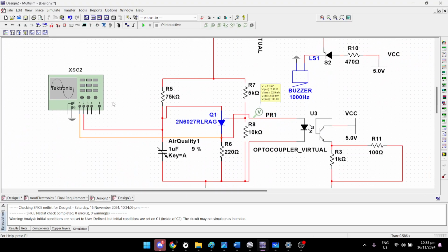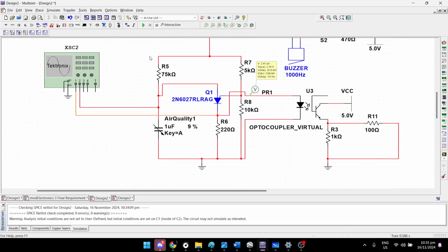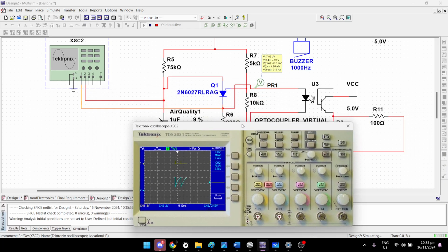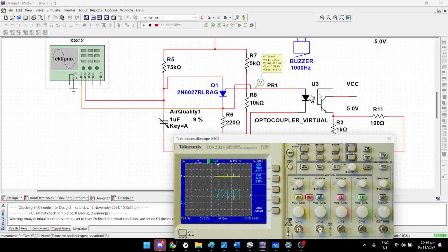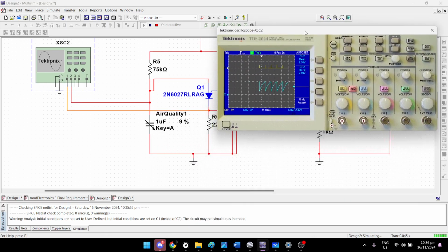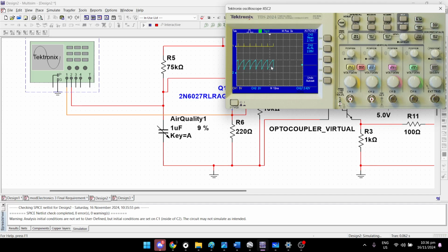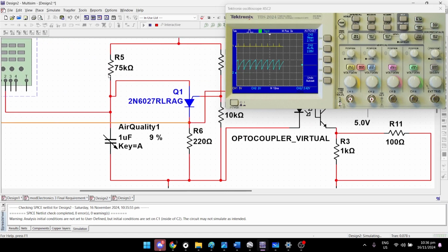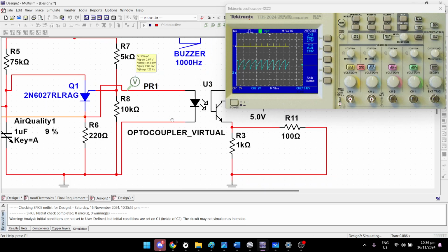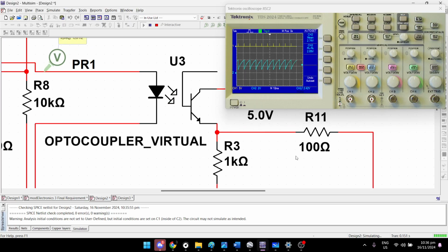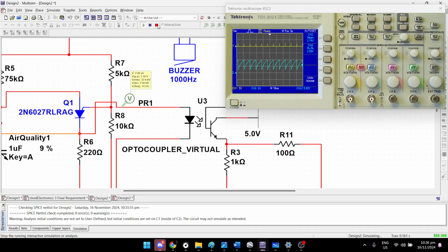And lastly, we can check the output of our pulse generation. So this is just a simple UJT/PUT circuit taught in our Elecs 3. Here I'm taking the output in this capacitor, which is just the relaxation oscillator, and the output that we have is actually here. So we can see the optocoupler is spiking. For example, it spiked there. Every spike is denoted here. We can see the impulse, and that is a type of data that we can use.